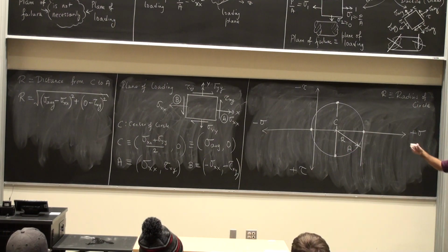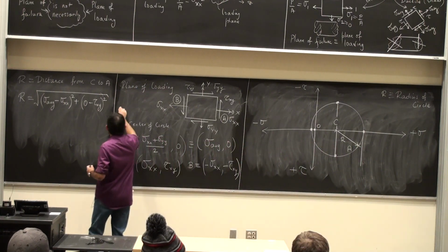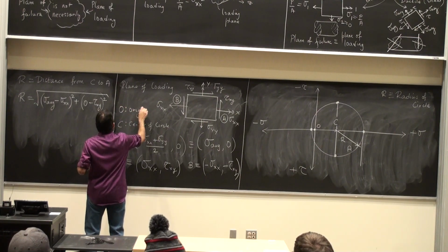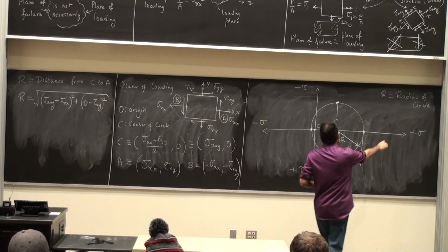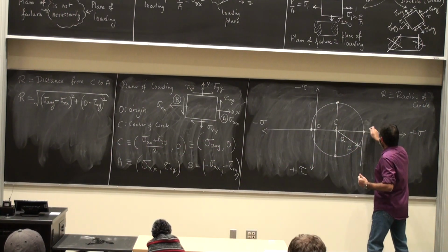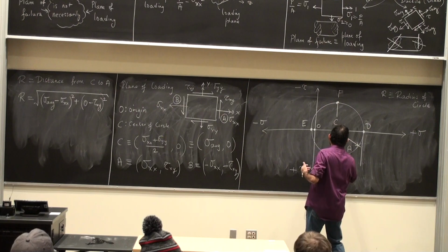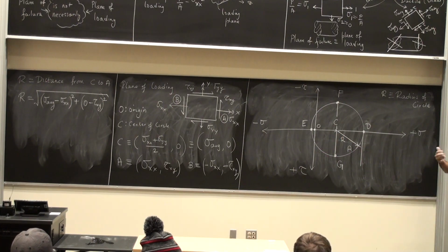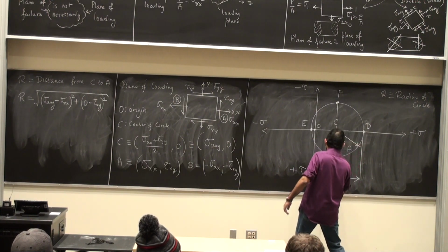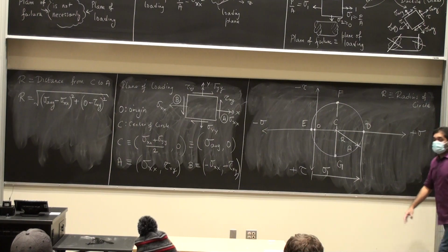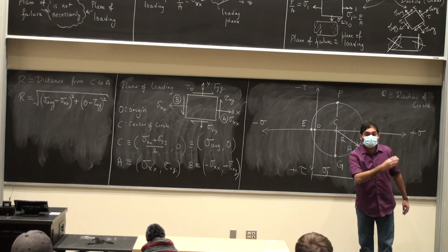The distance from the origin, which is the point O, so O is the origin. Okay, distance from the point O to the end points here, which I have as D, E, F, and G. Distance from point O to point D is the first principal stress value. So if I draw the circle, I have everything. This is equal to sigma 1. Distance from point E to point O is the second principal stress value, and you can see that that can actually be a negative value.